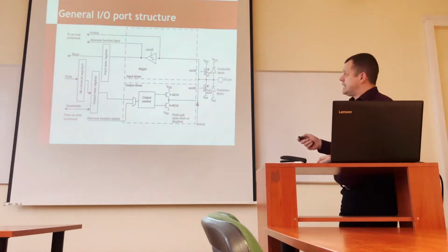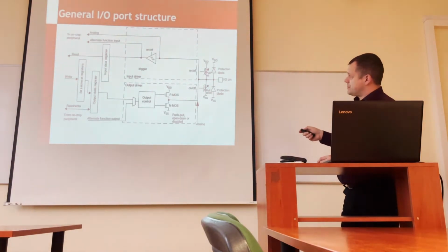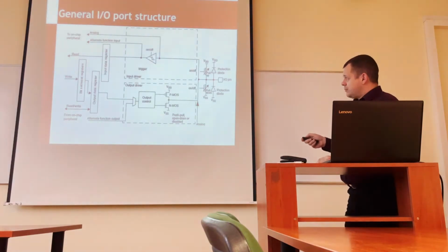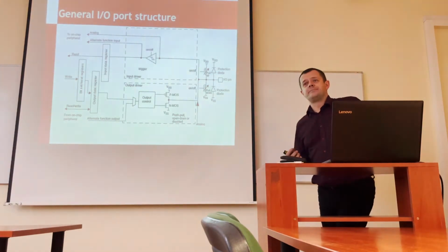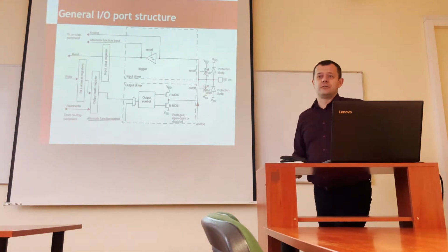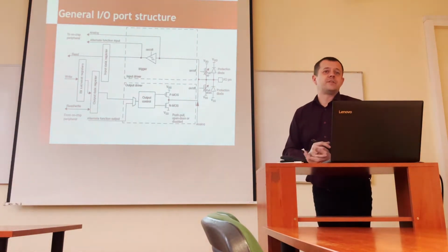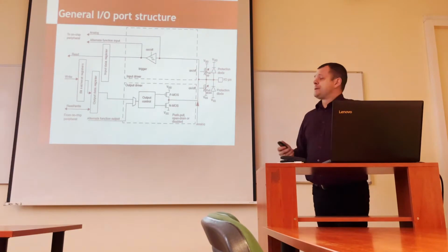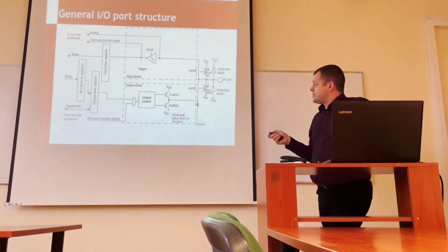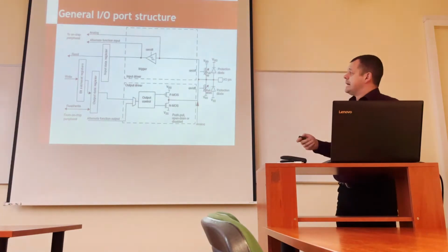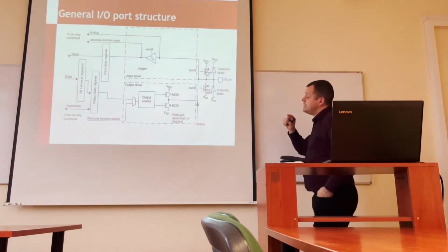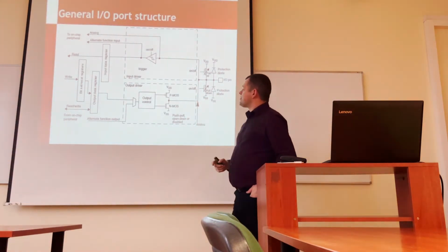This comes from the fact that the input has some input buffers, an input driver, and the impedance of the input driver is very high, ideally infinite, while the output driver's impedance should be zero. A perfect output driver should have no impedance at all. Then it would theoretically be possible to drive with this output driver infinite loads, infinitesimally small loads, large loads that require a lot of power. In reality, of course, neither has infinite impedance, nor zero impedance.